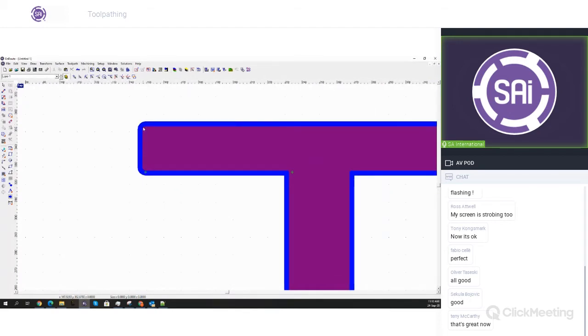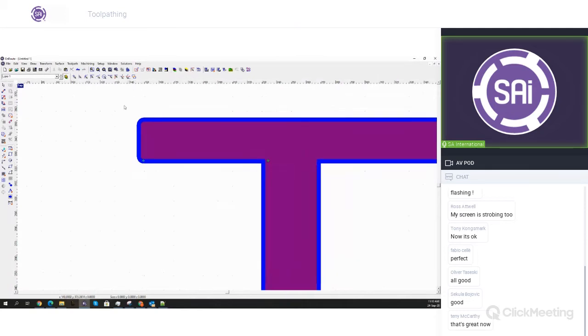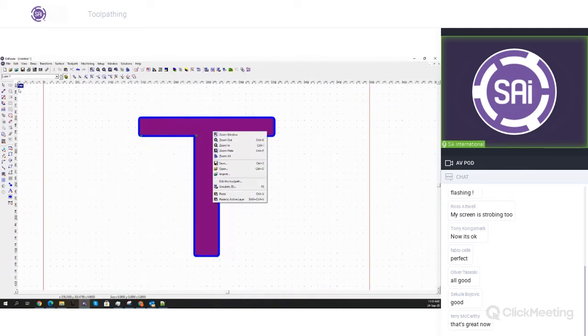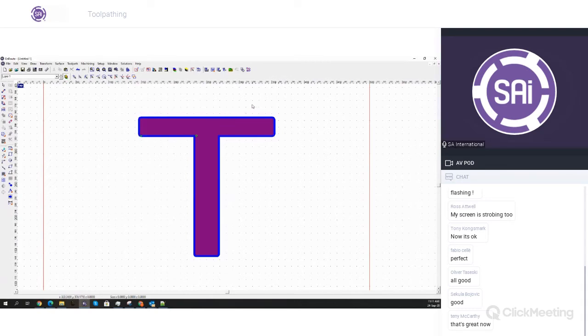The thing here is EnRoute does not calculate the differences in between tools. So you cannot use an 8mm bit for one cut and a 4mm bit for the other one. Something to keep in mind. And previewing the toolpaths like this, you can simply do by hitting F9.